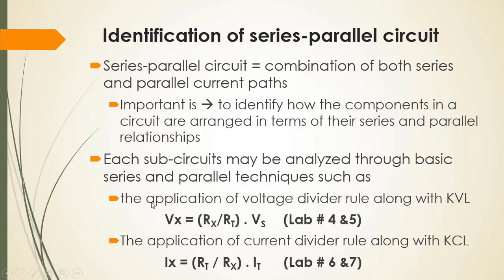For example, for the series circuit, we can apply the voltage divider rule and Kirchhoff voltage law. You can see the voltage divider rule where Vx is equal to Rx divided by R total into Vs, as we have seen in lab number 4 and 5.